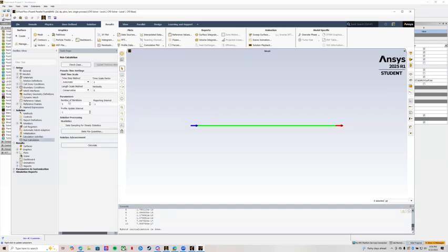Next, we're gonna go to our run calculations tab. So you're gonna want to run over 100 iterations at the very least. In this project, we chose to run 200 iterations just to be in a good range. Usually it's 200 to 300 is the range to do it. And then you're gonna go ahead and press calculate. Now you're gonna have to give it some time to calculate all those values.